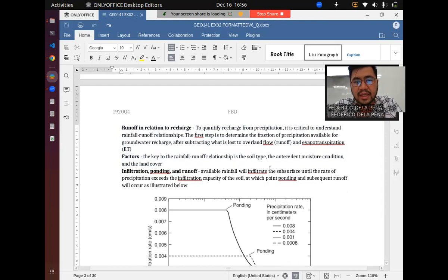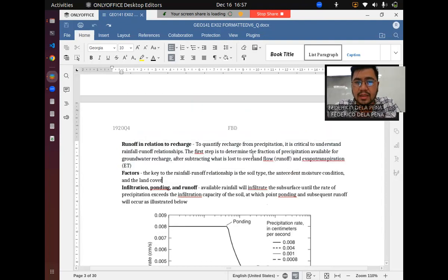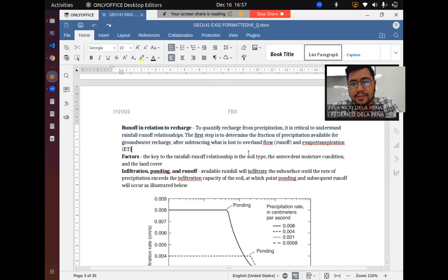Now, there are certain cases, particularly for agricultural modeling or flood modeling, where you actually have to look at the real time or time varying quantities of runoff and recharge. I'm going to emphasize here that precipitation is the water that's entering your watershed, and it gets partitioned into your runoff and your groundwater recharge.